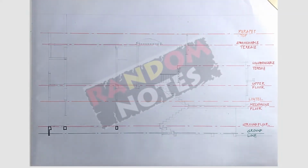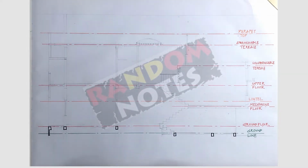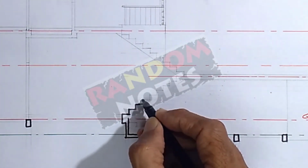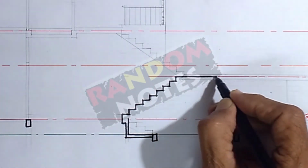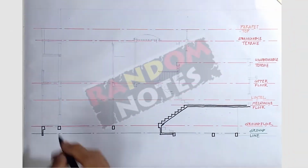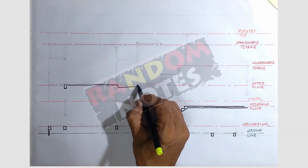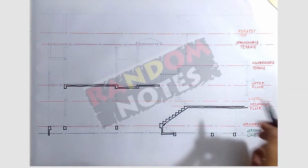The plinth beams of the ground floor, the staircase tied to the plinth beam at ground so as to have a proper transfer of load onto the structure. Now the upper level conventional slab with its system of beams at the edge and the sunken slab wherever needed.